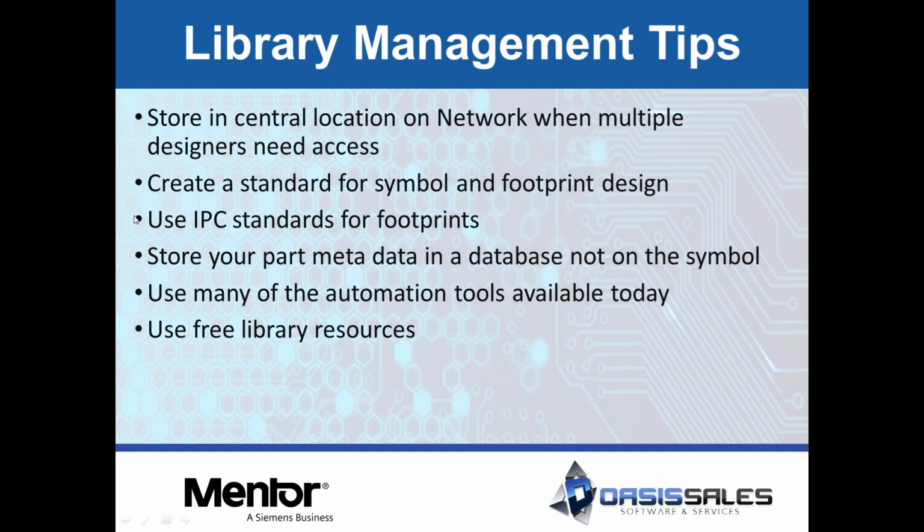Making footprints, try to use the IPC standards. The IPC 7351B spec is out there. A lot of the wizards that are available today are based off of it. It's a great standard. Everyone should be using this.